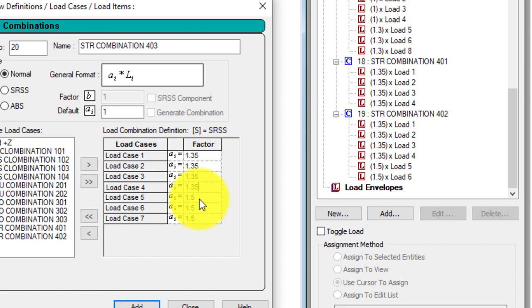The designer determines which one he considers to be critical. So you might not use 1.5 to multiply all throughout. There is a factor recommended by the code that you can use to multiply one of them, maybe the wind load or the live load.